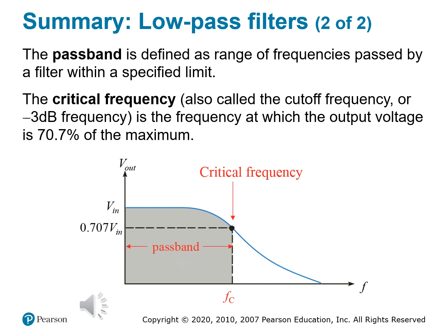And now what happens at the edge of this party? Well, that's where the critical frequency comes in, also known as the cutoff frequency. It's also designated as the negative 3 dB point, right? So at this frequency, the output voltage has dropped to about 70.7% of its original strength of V in. And why? Well, if you look at the graph, you'll see a smooth roll off beyond that F sub C. This is where the filter starts muting the higher frequencies, shrinking their influence in the circuit or your signal.